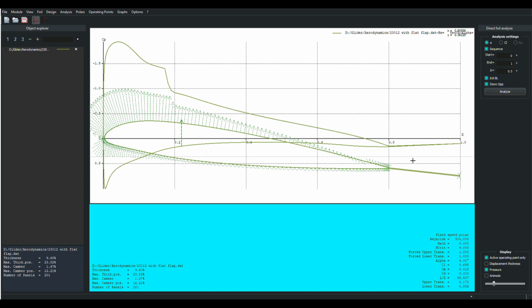It's generating a little bit of lift, so there's some pressure available here that causes this to have a slight slope to it rather than being absolutely flat and nothing's going on. So there's a little bit going on back there, mostly driven by what's happening here at the trailing edge. So nominally, no impact on the basic performance parameters of the airfoil.